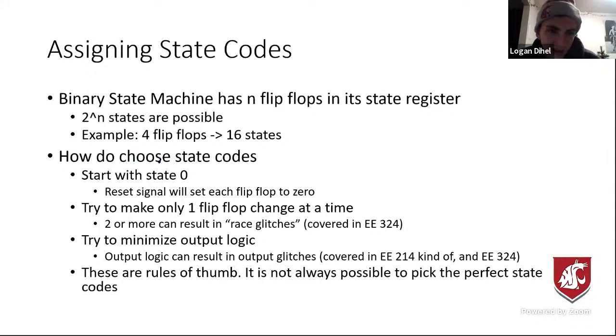Choosing state codes is more art than science. It's kind of hand wavy, and a lot of the time you can't get a perfect result, and you just have to live with it. So good rules of thumb: you should always start with state 0, so reset into state 0. Try to only make 1 flip-flop change at a time, if possible.